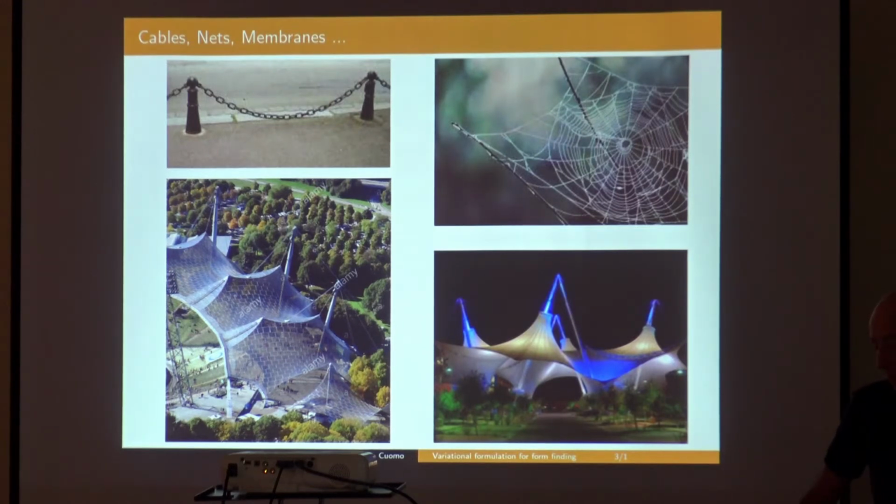But if you talk about 2D surfaces, membranes, you do not have a reference configuration either, because the membrane is not a proper shape. Also, if you remove the membrane from the support and you lay it on the floor, this configuration will not be stress-free, and this is a big problem. So we have, in some way, a change of philosophy.